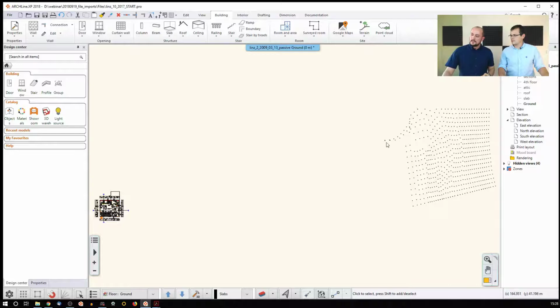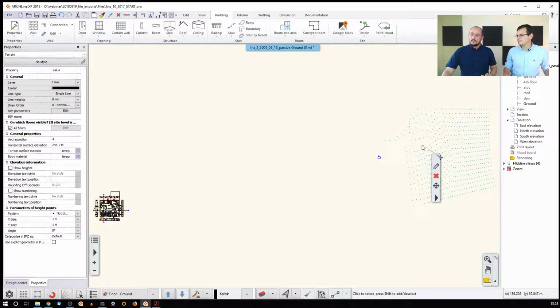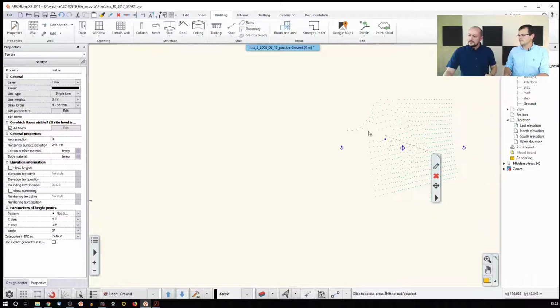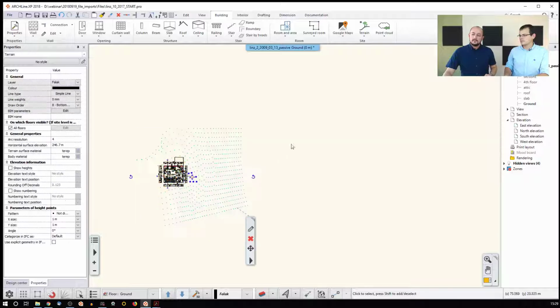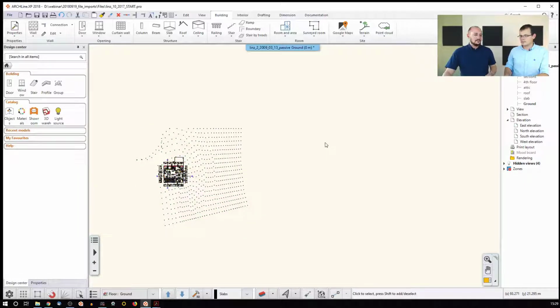See these here, these are the clouds of the measured data by an engineer on the field, and stored. It's quite similar to a point cloud, but we will cover that. It's a different topic. It's the height data, which is automatically turned into a terrain when you import it. You can move the building there, you can move the terrain over there, whichever is fine, but there will usually be one thing that you need to fix when you work with terrains that are imported into an existing model, and that's the height of the terrain and the position of the building.